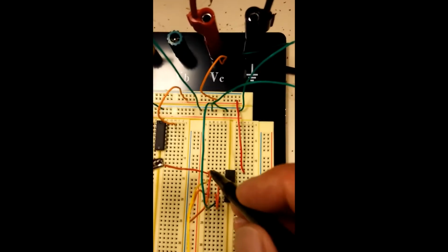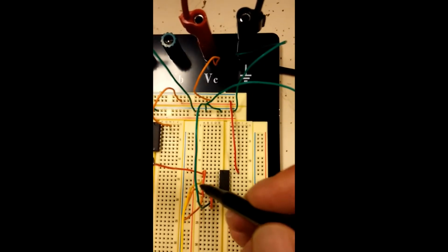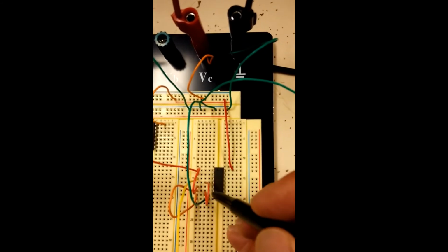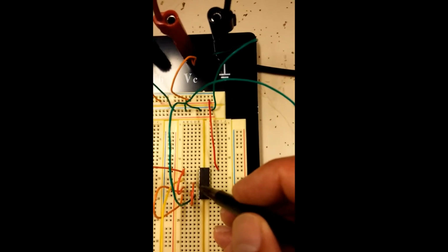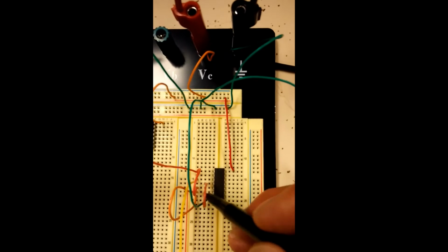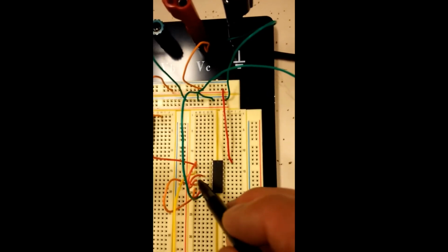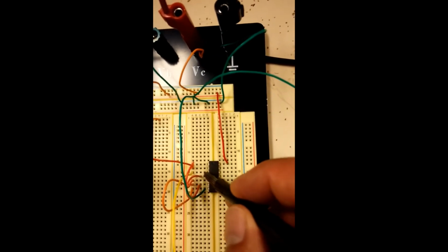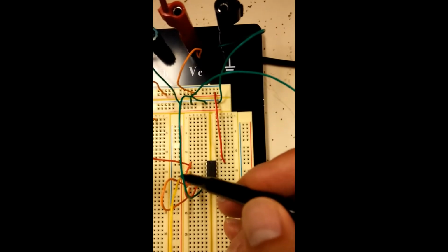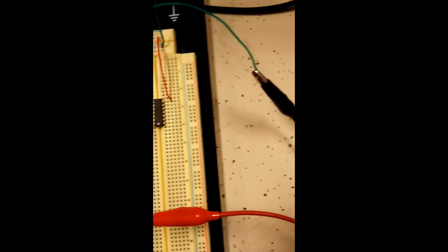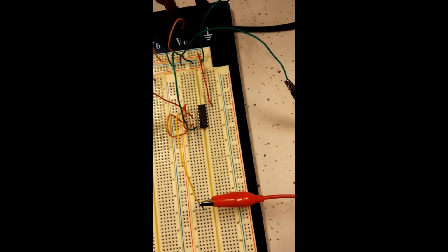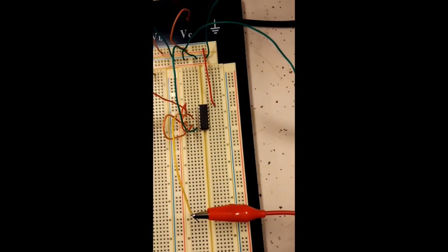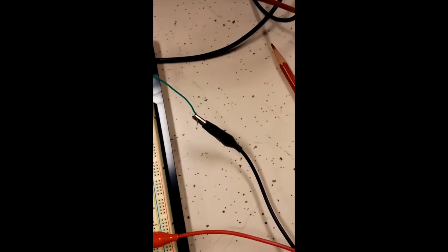All right, and the 2 is Q bar, connected to data, which is pin number 5. Let's make sure I got it right. And then you have this clock at pin number 3, yellow wire. So I have to feed in this power signal, square wave signal from the generator. That's what we have, generator.